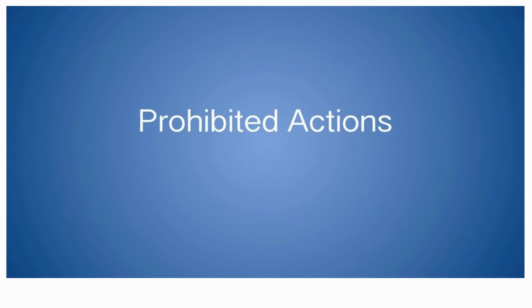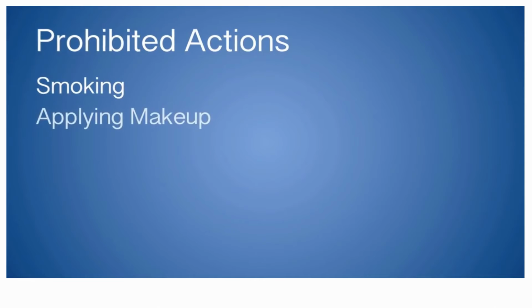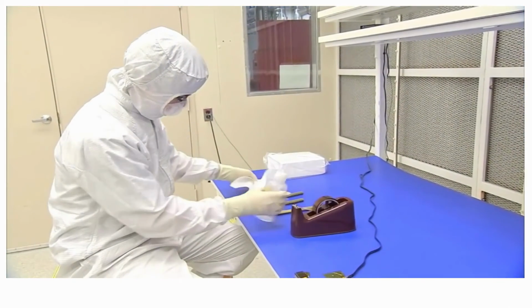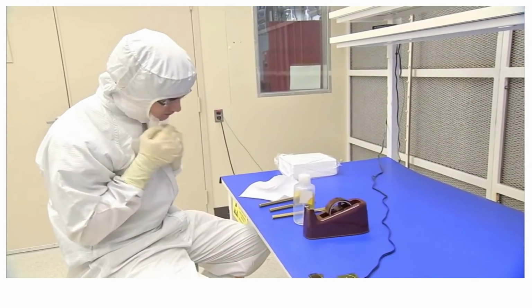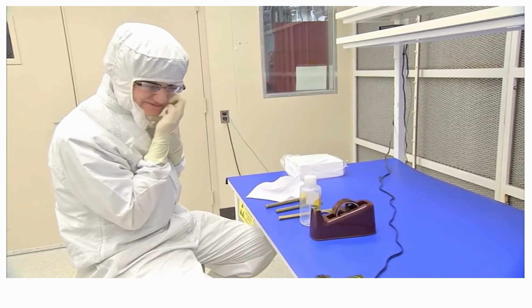Prohibited actions. While in the cleanroom, a number of behaviors are prohibited as they introduce unnecessary contamination. Smoking is absolutely prohibited in the cleanrooms, as it introduces a vast number of unnecessary particles into a cleanroom. Applying makeup in the cleanroom is also prohibited, as makeup is a huge source of contamination. Touching one's face with gloved hands introduces skin and oil to gloves, which then gets transferred to hardware and other